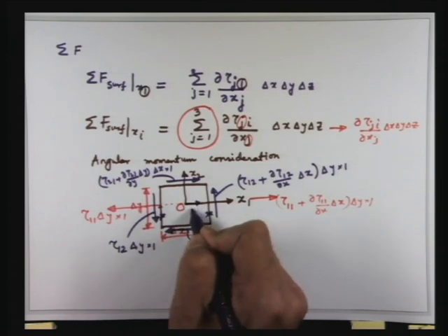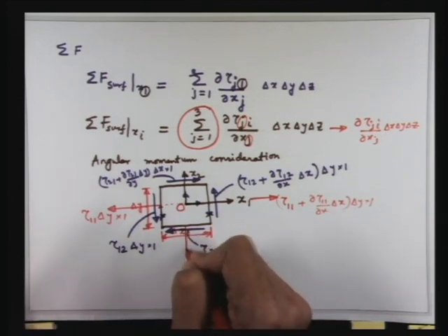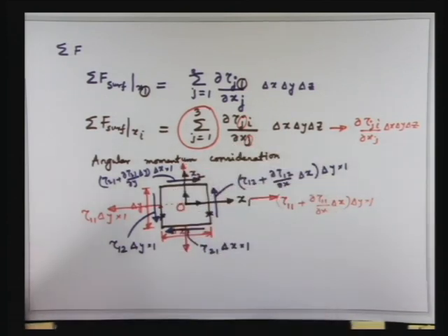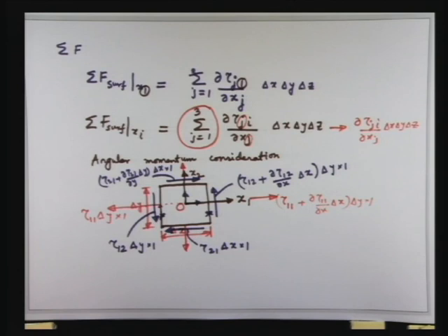Let us say these are the body forces, but body forces are not that important because they are not representing any couple. There are of course some normal forces also. I will show the normal forces on this face and this face, but I will not write the expression just to save time. These normal forces, whatever their expressions, do not matter, because they do not give rise to any moment with respect to the z axis passing through O.